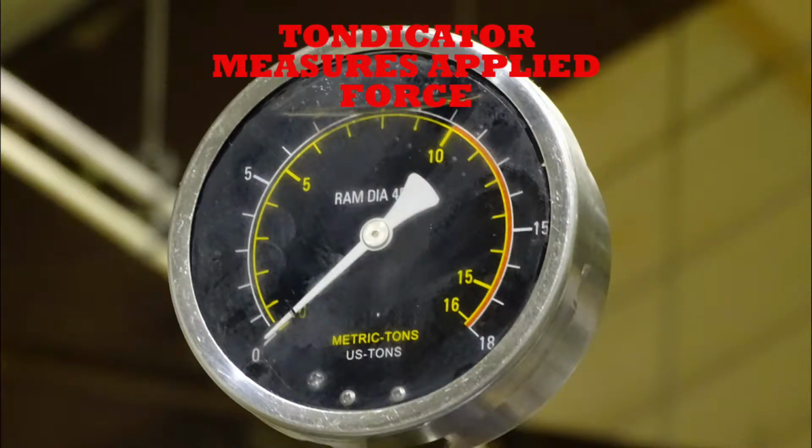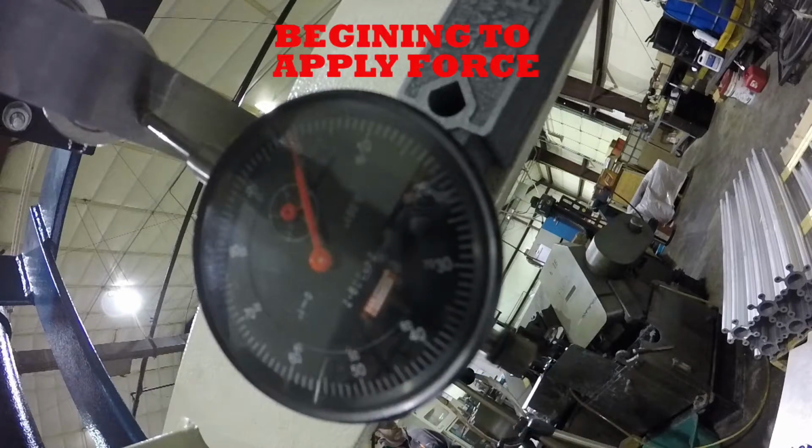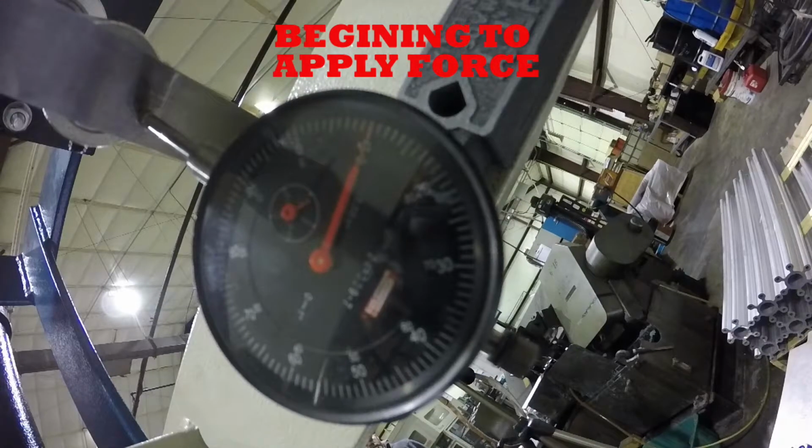The arbor press has an indicator located at the top, so we know how much force is being applied. We also used a spring-loaded indicator that was positioned directly under the load cell. This allowed us to measure the amount of bend applied to the beam. We will now demonstrate our project by applying the force to the beam.